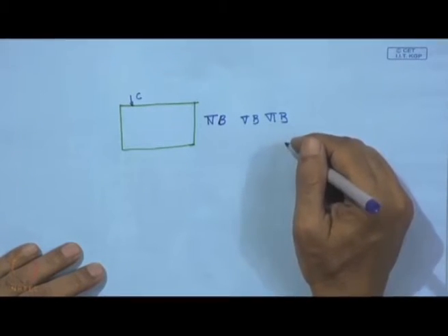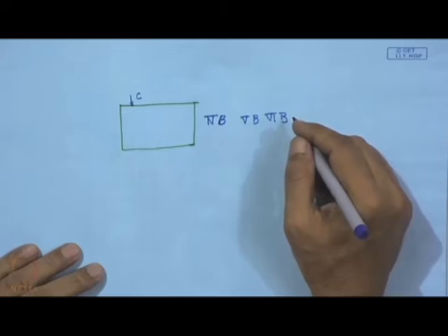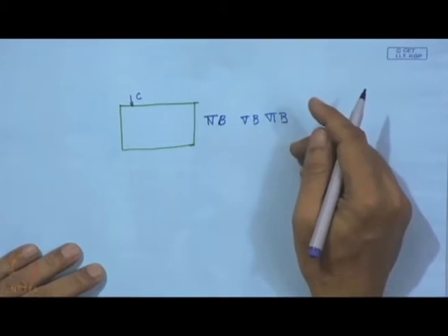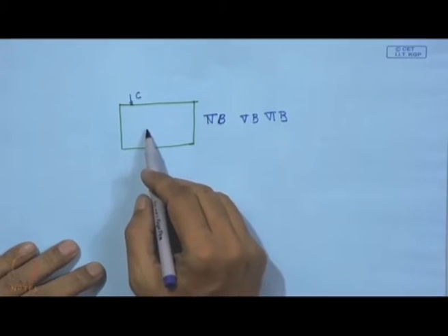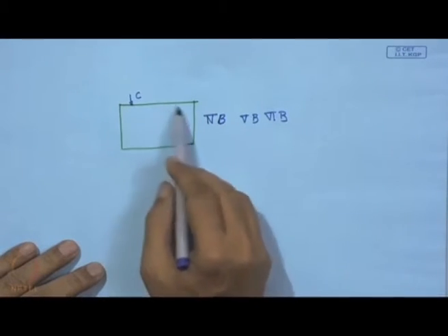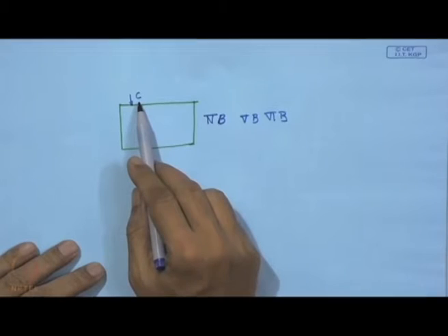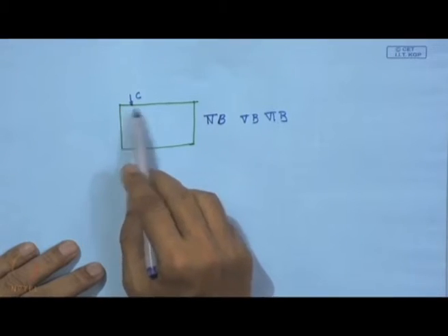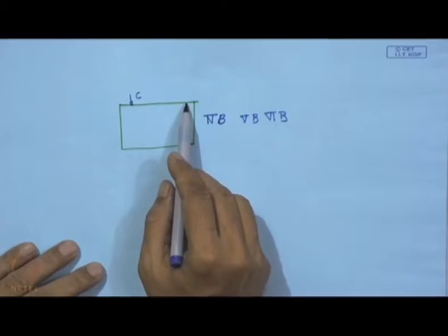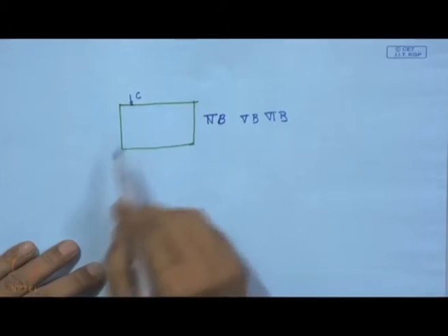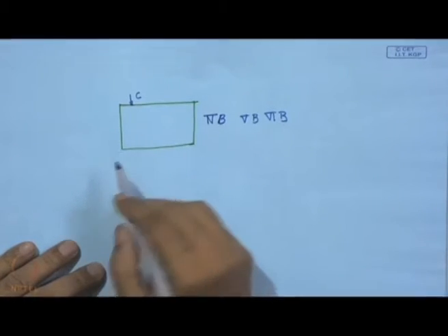All these materials are known for their great tendency to form carbide. So, if those materials are present within the body, then this carburizing process will be one effective process to enhance the surface property, and this is actually what we mean by carburizing. So, that is the whole idea.